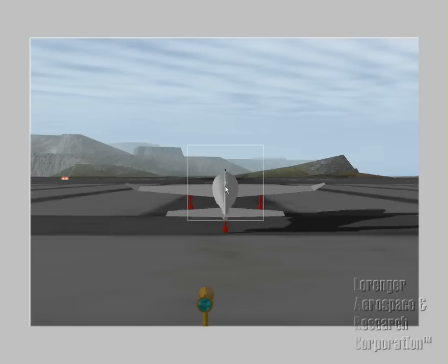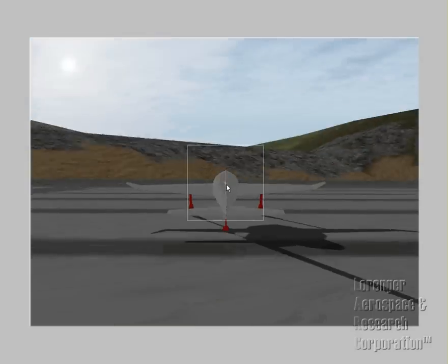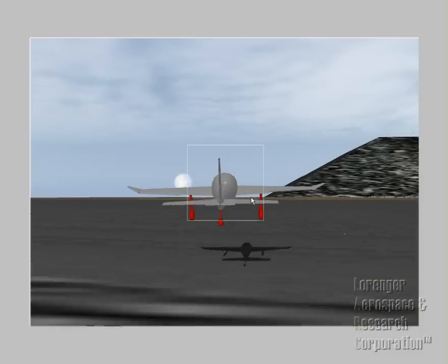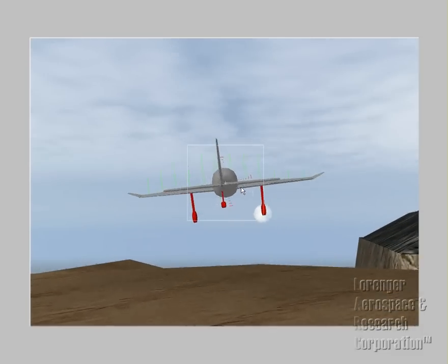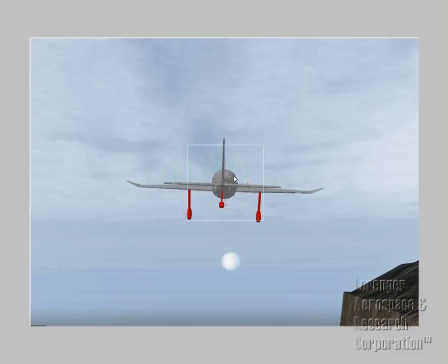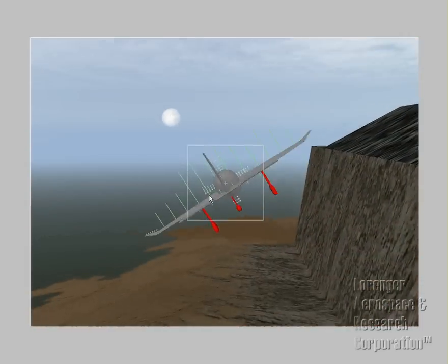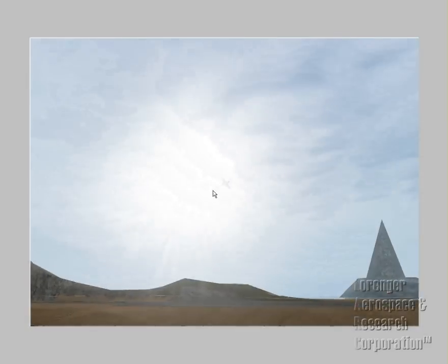Really. So here, we quickly test fly it. You can quickly show the controls. See how it's spinning out of control here? That means the tail wheel hasn't been set. It doesn't steer. The tail wheel does not steer with the rudder, and you will set that in advance. My error. But at least we're up in the air. We're flying. We're realizing that she's carbureted. She'll stall upside down, and she maneuvers decently.